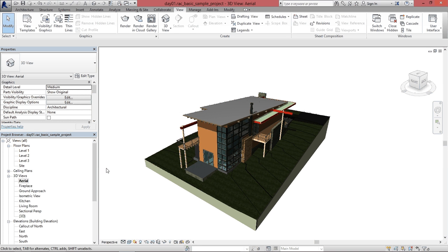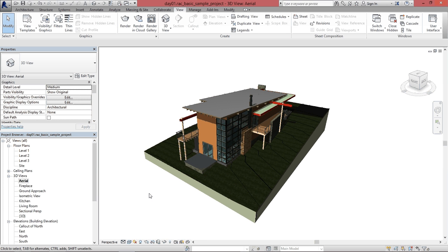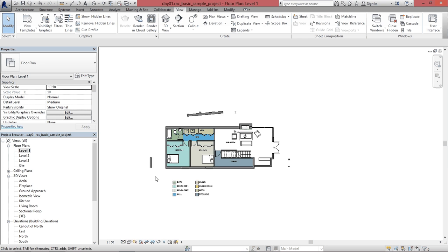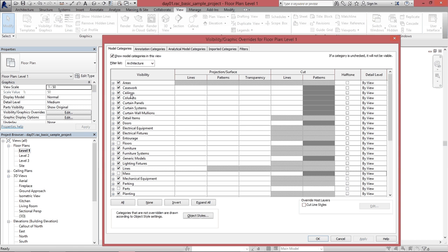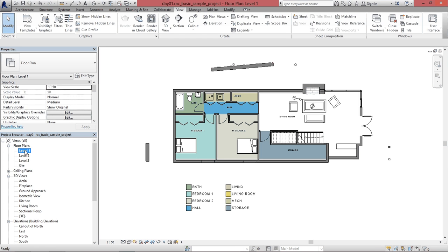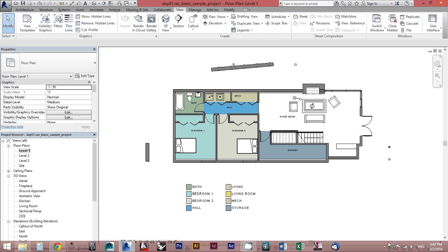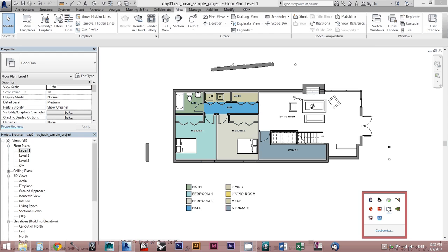So great. This is, I think, a good introduction of how to deal with views and how to start thinking of changing different features. Now, the power of hiding in different views only by using the VV, unchecking something, means that we can duplicate this as many times as we want and have different views with different conditions of visibility, which adds an incredible opportunity to realize different things with the same project. Okay, I'm going to leave it there. The next step is actually putting together some features. Okay, good. Next video, next.